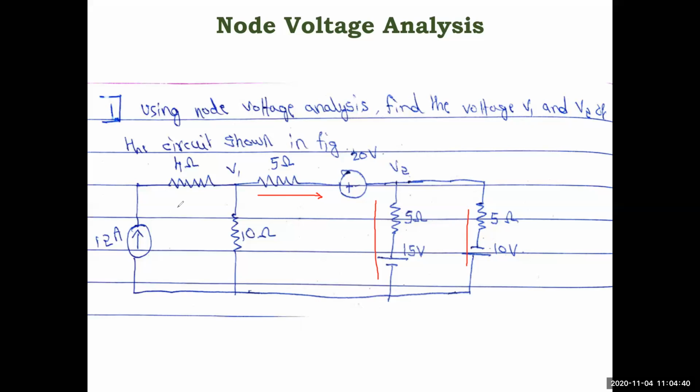So first, we will remove the 4 ohm which is in series with this, and these three voltage sources in series with resistance will be converted into current sources in parallel and simplified, using the source transformation techniques. You write down this network one more time in the solution.